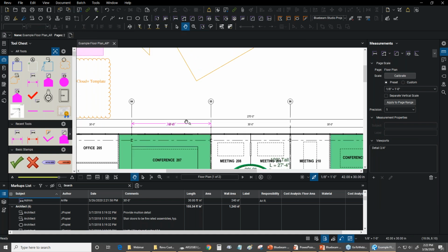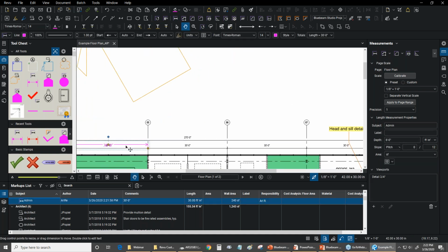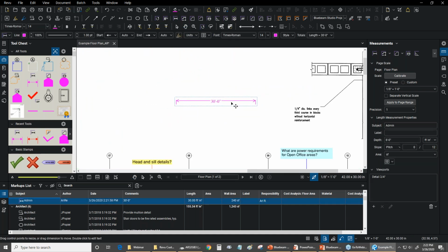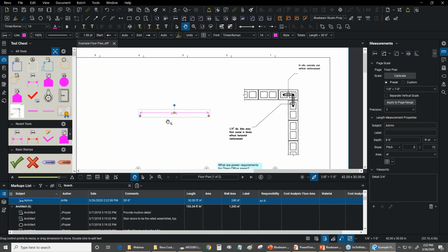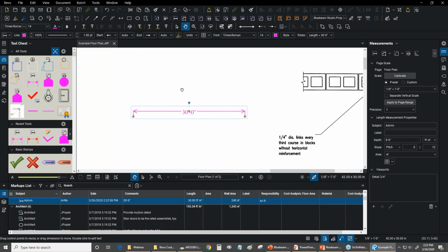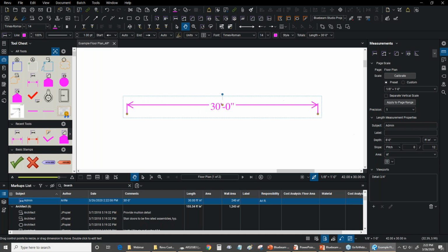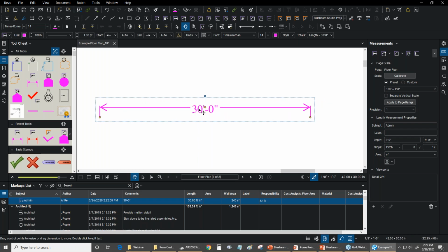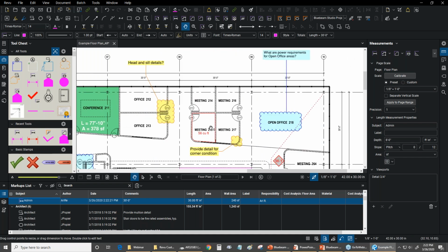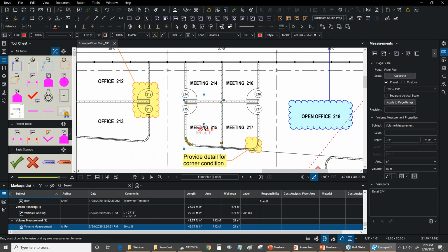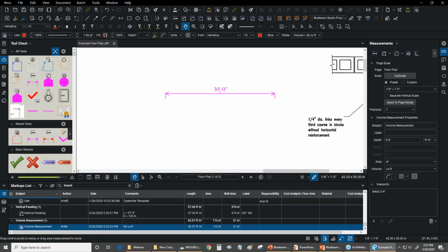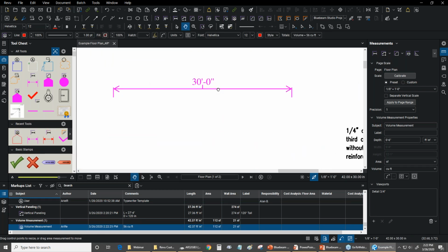So what I'm going to do is take this length measurement, and before I move it into the viewport, because that's obviously the fun part, let me show you guys some formatting options. I might have shown this a little bit before, but I just want to make sure that you guys are familiar with how to make this measurement look the way you want it to. You can hold shift and move text independently, just like we did before with dynamic fill with this room. We can just hold shift, click, and move this text anywhere we'd like without moving the measurement or the length.